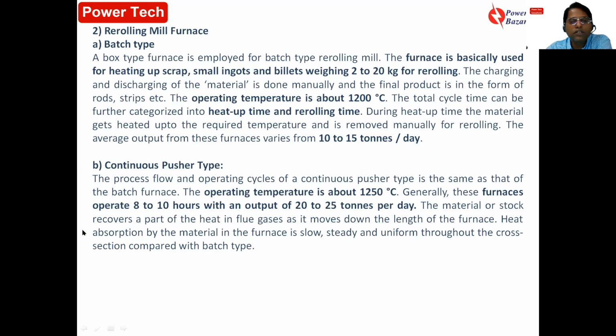The charge moves due to pushing of the charge, so that at the discharge end the burner throws heat into the charge, and the charge moves and the gases move in the opposite direction, which heats the entry charge, and the exit charge is heated with the burner, and you get uniform temperatures.